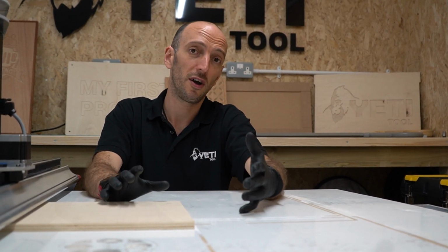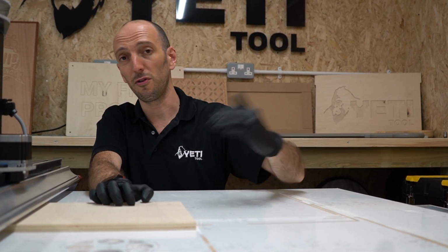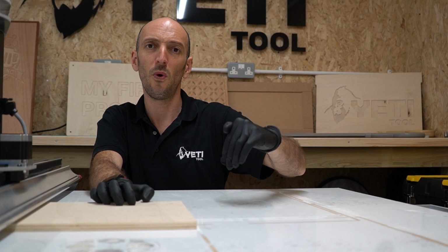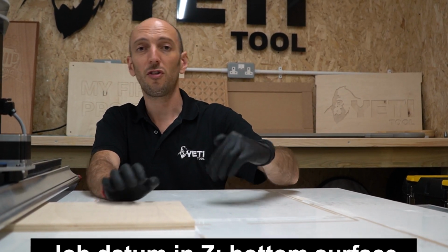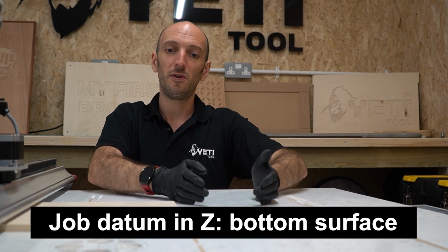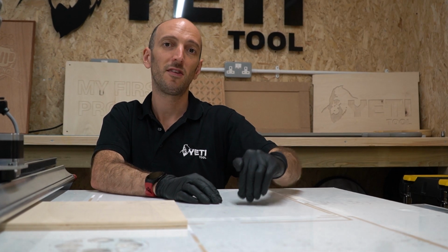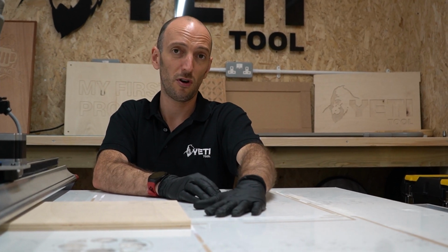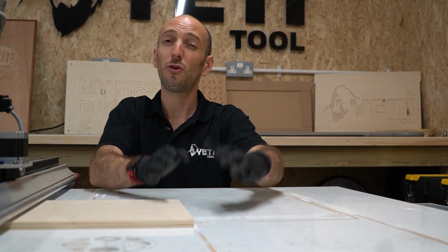But one of the downsides of referencing the top is that if you have any variation in your material thickness, you don't actually know where the bottom of your final cut depth will be. And so for that reason, if you need to be super accurate in your final cutting depth, it's best to reference the bottom of your stock. The main reason though that that's not popular is because it's just a bit more difficult to access. So it's horses for courses, and really you need to pick whatever is best for your application.